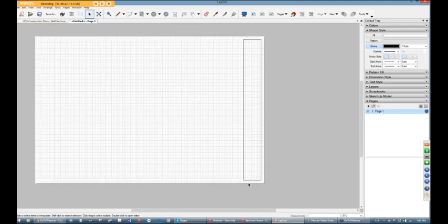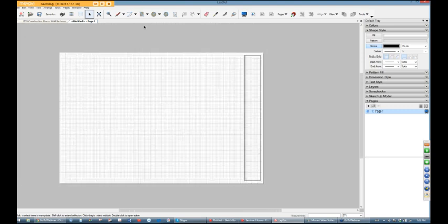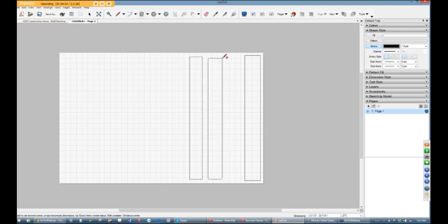If you don't like the box, you don't have to have the box. You can also do it with the rectangle tool, which is an R, or it's this drop down up here. You'll notice here in Layout there are several different kinds of rectangles. The typical one that we would use: just grab one corner, drag this out and click, and you'll get a rectangle. One that a lot of people use on their title blocks is rounded, which gives you a rectangle with rounded corners.